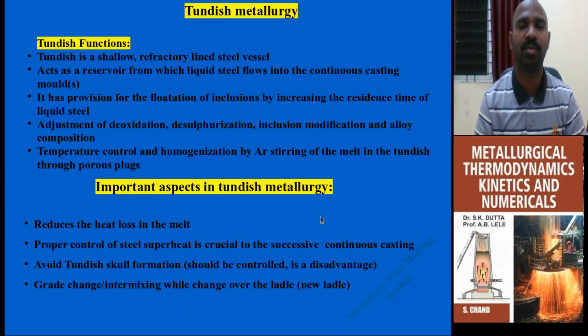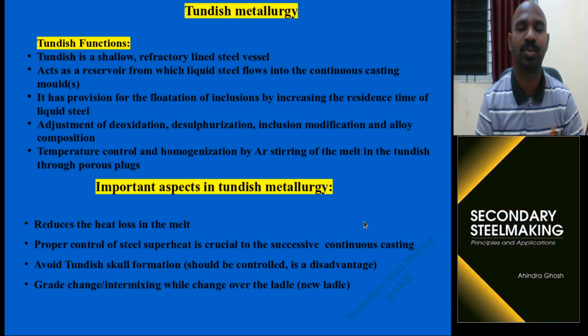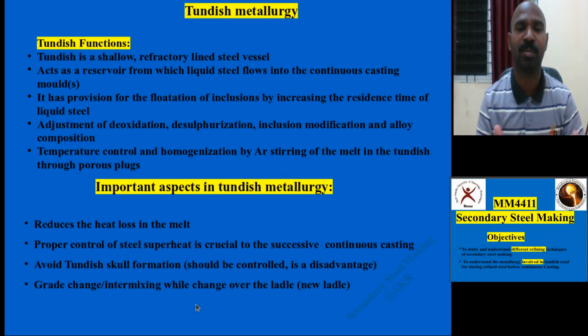It needs to be covered with a tundish cover, the slags which are formed need to be continuously removed, and argon gas should be sent continuously, allowing it to stir. These things need to be taken care of. These are the important aspects.